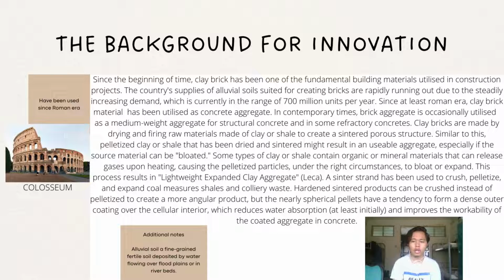Hardened sinter products can be crushed instead of pelletized to create a more angular product, but the nearly spherical pellets have a tendency to form a dense outer coating over the cellular interior, which reduces water absorption at least initially and improves the workability of the lightweight aggregate in concrete.